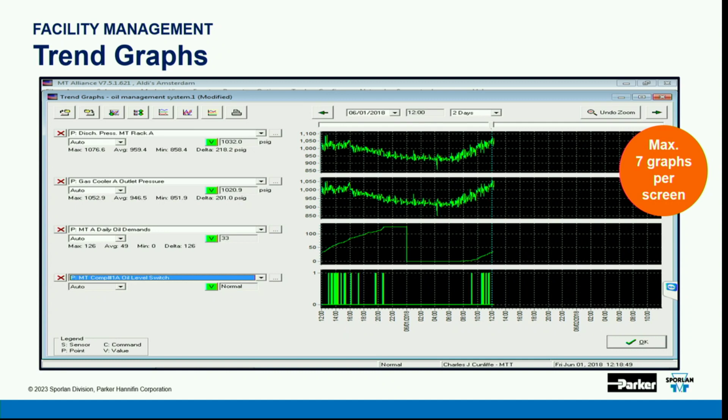And then a week or 2 weeks or 3 weeks later, you open that case up, you pop open that trend graph that you saved, and guess what? You can go from real time and scroll back for the 1, the 2, the 3, or the 4 weeks and find out where the wheels fell off the wagon, okay? So you don't have to add anything onto the system to try to find the trouble. That ability is for you in trend graphs. So all of our nodes have the ability to do trend graphing.